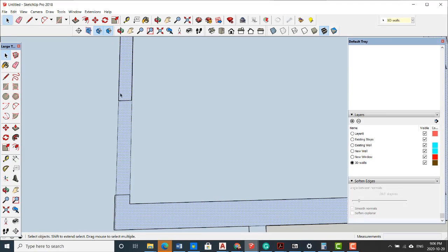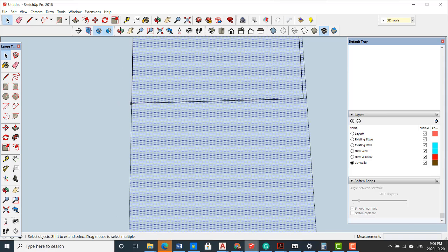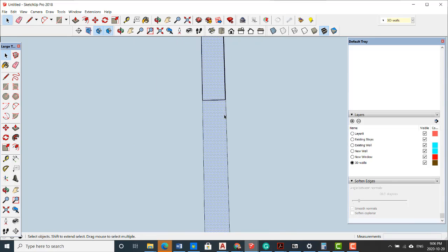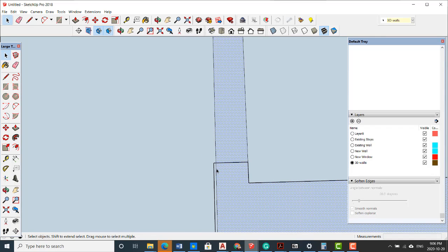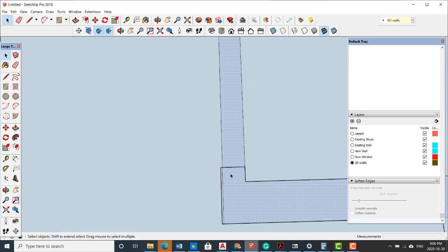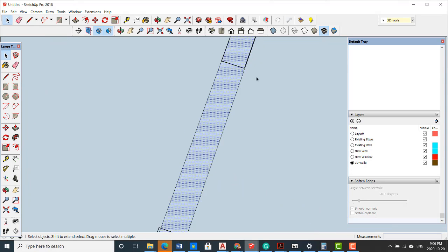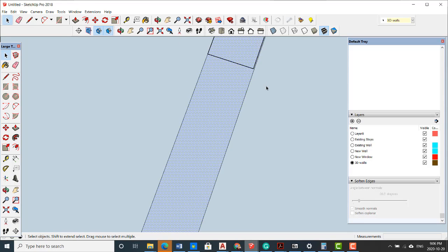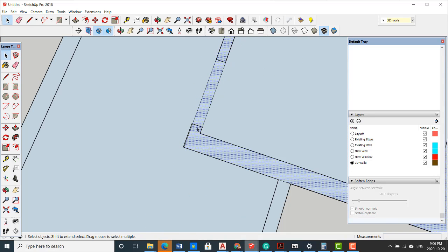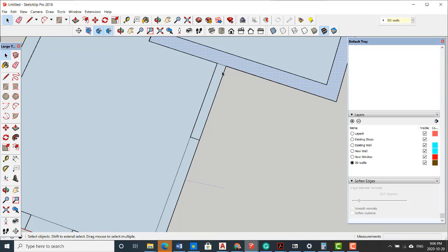So again, there is something, see these two walls in AutoCAD, they are not aligned. See, this wall is offset compared to this one. So it's not a big deal. The only thing is when you're adding your door, you have to be careful so you don't place it in the wrong place. Okay? So for this wall, I would pay attention when I'm doing the doors.